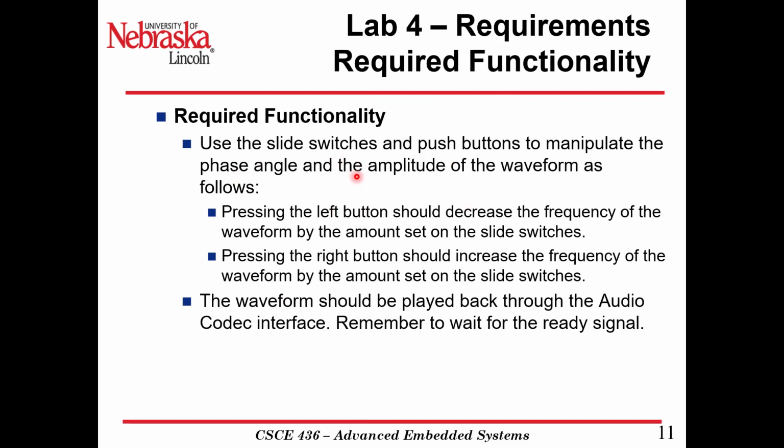Required functionality: use the slide switches and push buttons to manipulate the phase angle and the amplitude of the waveform. So phase angle is essentially your frequency, and your amplitude would change the Y value of your axis, your voltage amplitude. Pressing the left button would decrease the frequency by a set amount on the slide switches in a Q2.6, and then the right button should increase the frequency by that set amount.